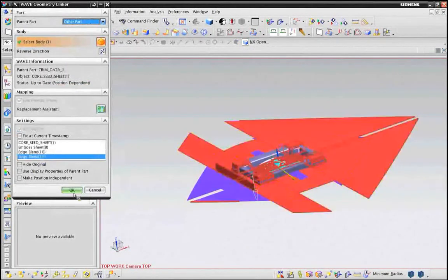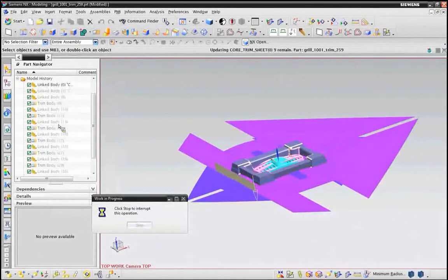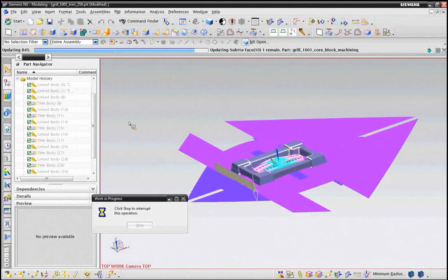And typically in any engineering process, I'd probably have to develop that parting line, spend a little time developing that parting line. But for the purposes of this presentation, I'd already done that work. So all I have to do really is go back in the history of the parting line and reselect the new faces that I want to use as the parting line. NX has that power and capability.